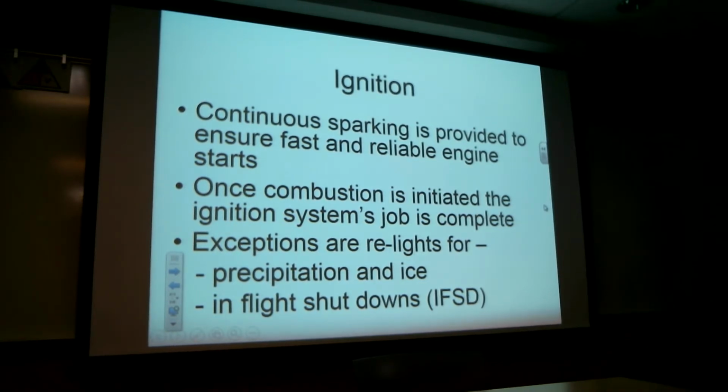The volcanic ash isn't only abrasive to the engine, it is, but the other part of that is that it will choke air supplies off inside the engine, air sensors, and that will cause the engine to shut down. So you need to have a good, reliable ignition source running during those time frames.